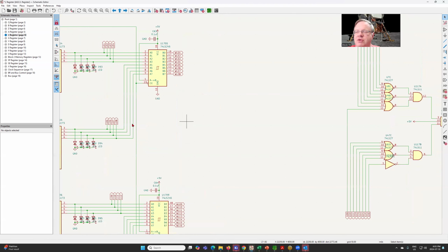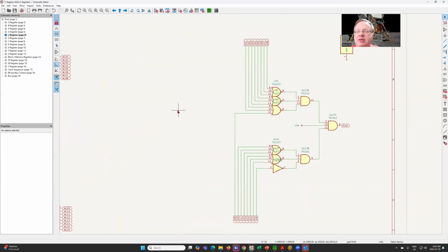Now, there's one other function I'm going to add to the L board. As you start realizing how to fit all of the logic and the control instructions together, you start to figure out that the backplane connectors I'm using have 96 pins, and unfortunately, if you start adding all the different write lines for the different registers and the control pulses, you easily get well over 100, probably 150, 160 different potential connections.